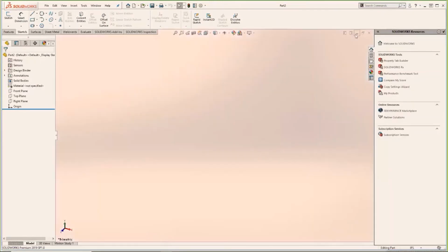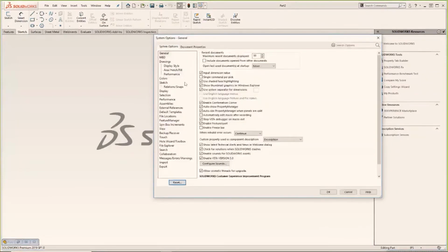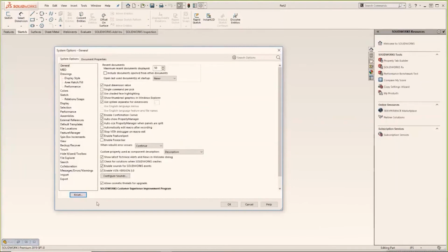So if I've ever been in SolidWorks and when I load up my new version and I'm getting this error loading the toolbox, issues adding toolbox components into my assemblies, most likely what it is, I created a new data location, or my company created a new data location. If I'm on a shared toolbox or a PDM toolbox, I need to make sure I'm pointing to that.